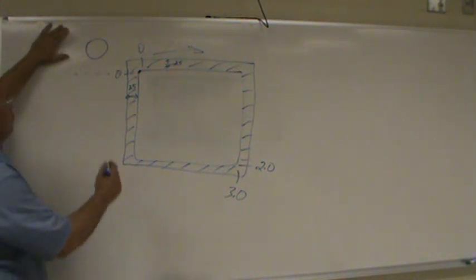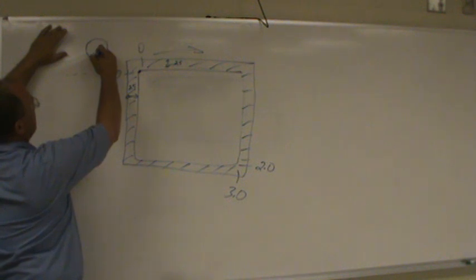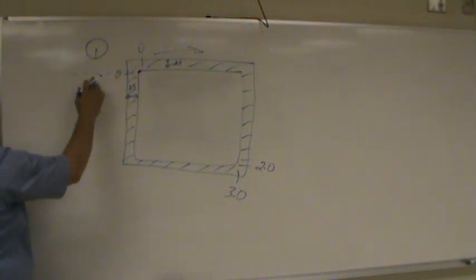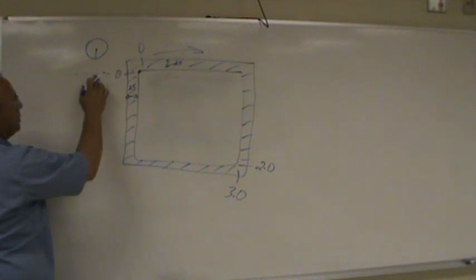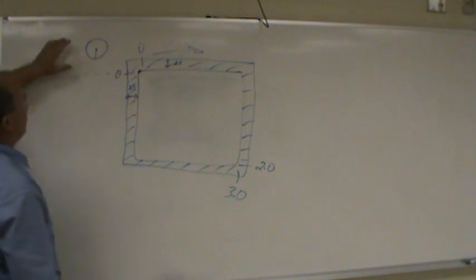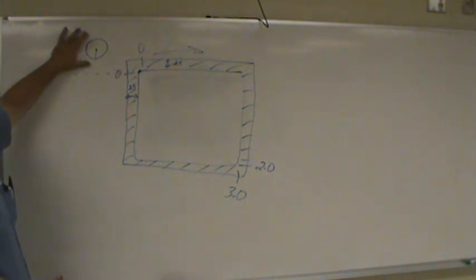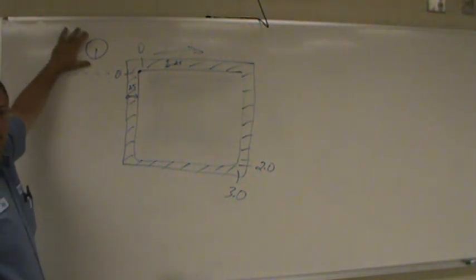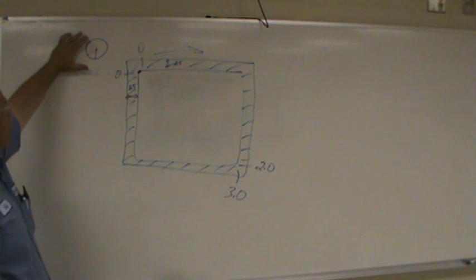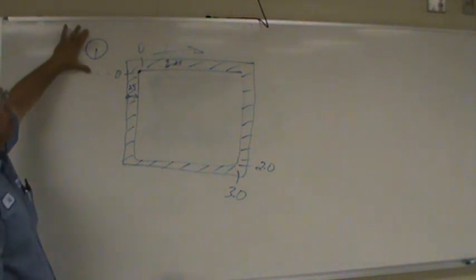By rule, you have to stay the radius value of your cutter. So if this is a 1/2 inch cutter, you have to stay at minimum 1/4 of an inch off your part. By rule of thumb, I think I'm going to use a 1/2 inch cutter, and I'm going to stay a diameter off my start point. That means I could use up to a 1 inch cutter.